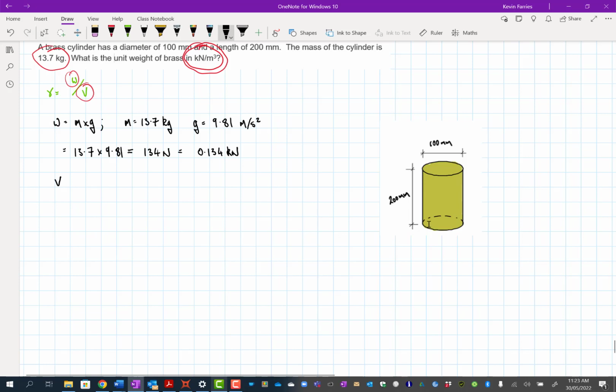And so the volume is equal to cross-sectional area times height. Now the area is a circle in the case of a cylinder. In school you usually write this as pi r squared. In engineering you usually have the diameter of objects, not their radius, because you measure it with a pair of calipers or something like that. So usually you know the diameter. So the equation we usually use for a circle is 1/4 pi times diameter squared. And then we're going to times that by the height to get the volume of this cylinder.